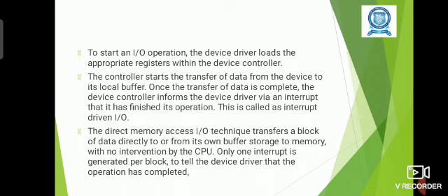One way of performing the data transfer in between the CPU and the input-output device is the interrupt mechanism, called interrupt driven input-output. Any input-output device will intimate the CPU and get service from the CPU by sending an interrupt signal. As a result of the interrupt signal, the CPU will execute the device code.